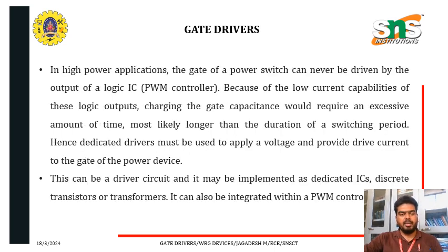In high power applications, the gate of the power switch can never be driven by the output of a logic IC, which is the PWM controller. Because of the low current capability of these logic outputs, charging the gate capacitance would require an excessive amount of time, most likely longer than the duration of the switching period. Hence, dedicated drivers must be used to apply a voltage and provide drive current to the gate of the power devices. This driver circuit may be implemented as dedicated ICs, discrete transistors or transformers. It can also be integrated with the PWM controller.